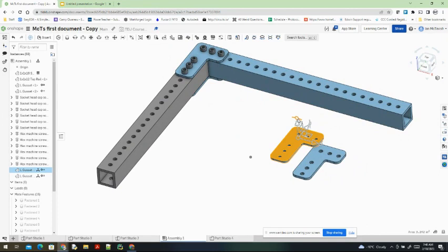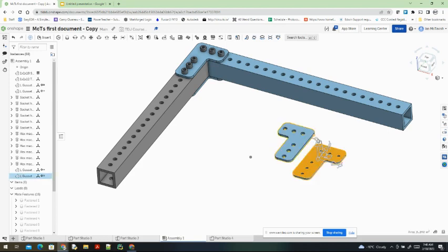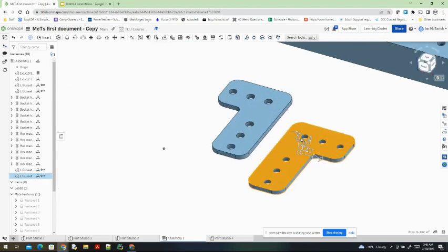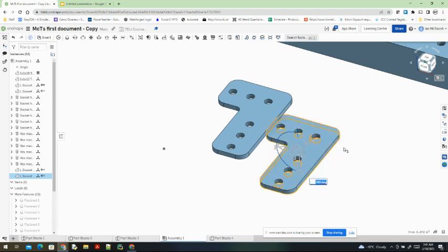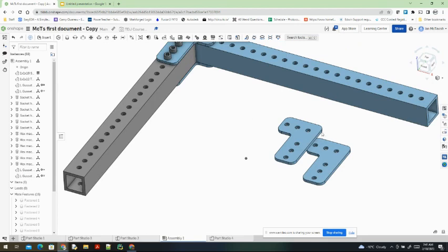So we're going to click this rotation, and when we start rotating, we can just type 180. Now we've got it flipped. So again, you click on the item, there's the triad manipulator, and you have the arrows to move and these circles to rotate. There are some other features that we'll go into detail later, but that's what we need for now.